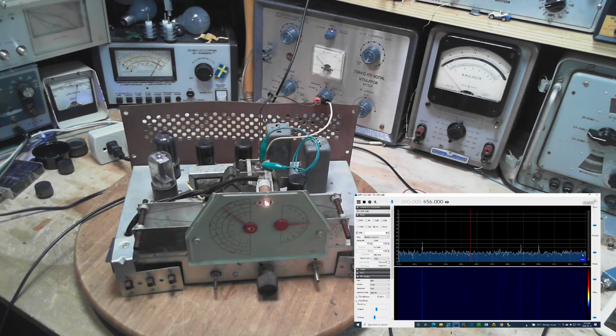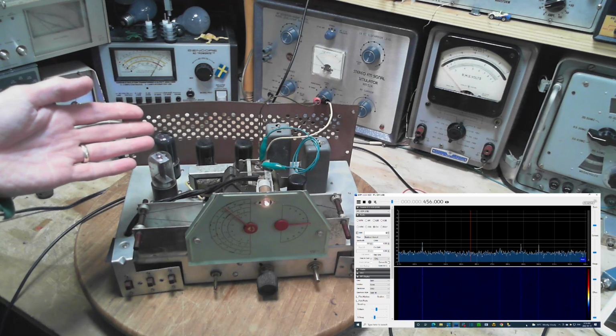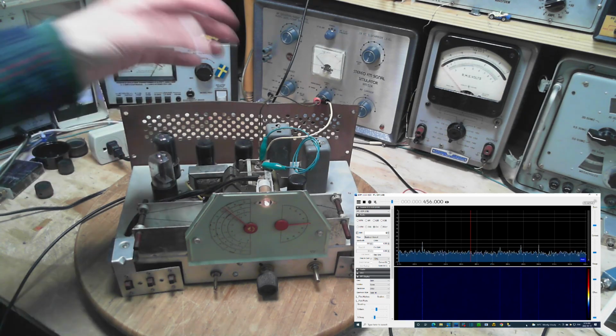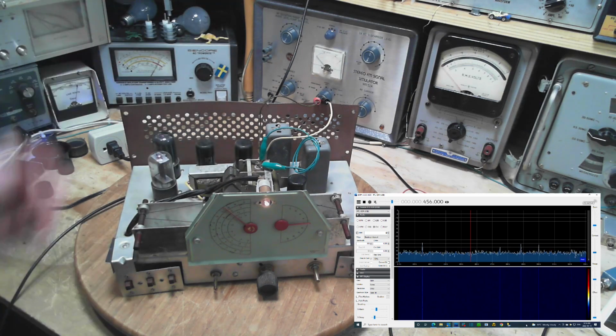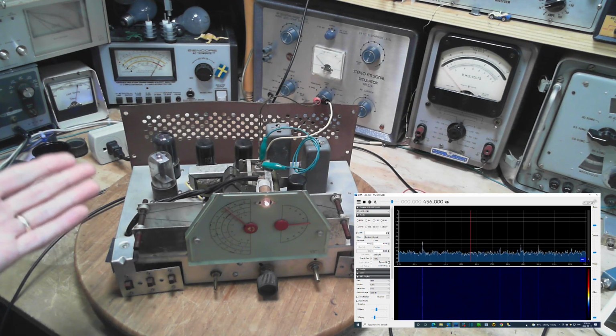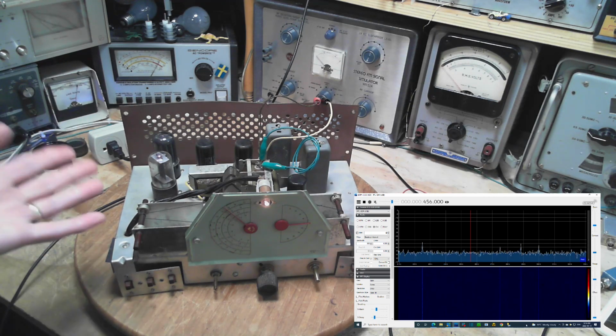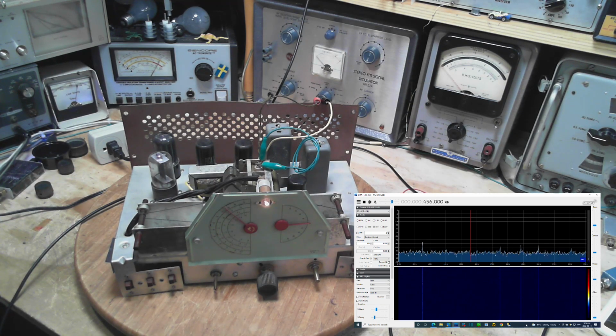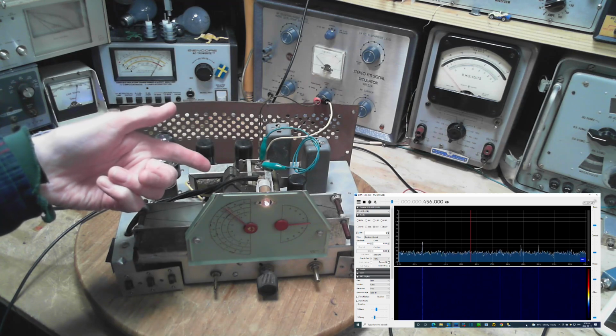So carrying on in that direction, these radios do produce a strong signal at 455 towards the end of the IF. They're trying to contain it, or there's some effort to contain it in the radio, but it is a radio frequency and it's traveling on wires, so some of it is going to be emitted to some degree. I misunderstood what the IF trap is. So now I'm thinking the IF trap is really all about preventing exactly what we're getting here, which is a bunch of noise at the IF frequency coming in on the antenna and going straight to the capacitor.